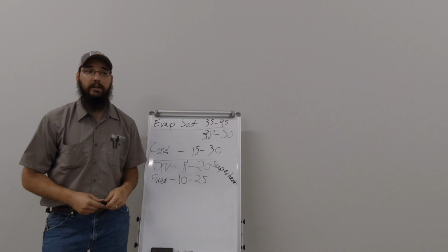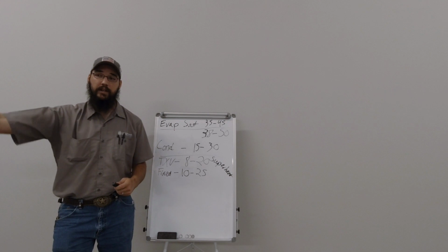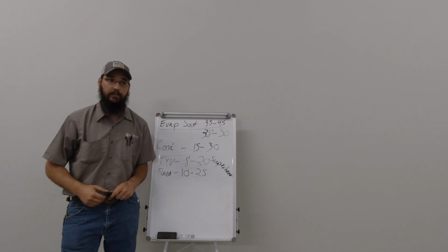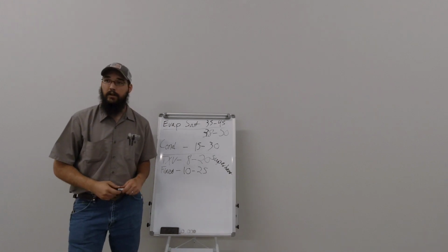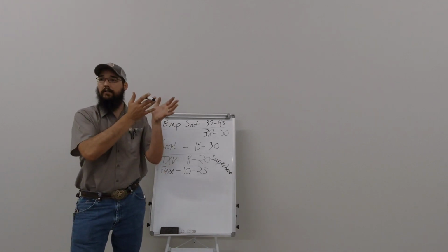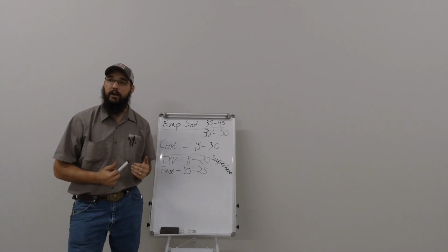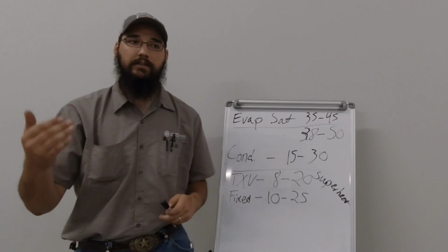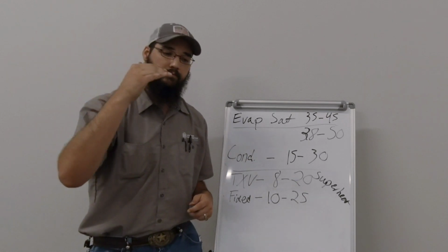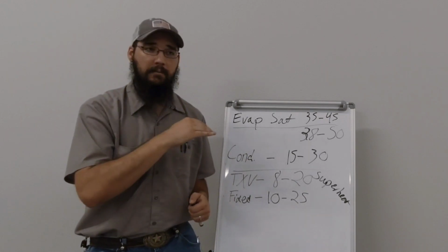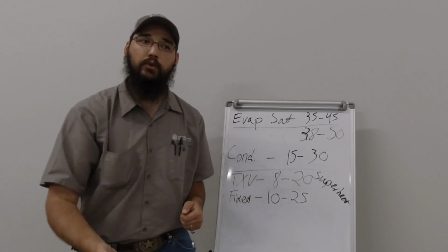The other way they can run is circuit 1, both compressors together without circuit 2. So next I'm going to stage off circuit 2 again, leave it off, and I'm going to bring compressor 2 on circuit 1 on. All right, so when I stage circuit 2 off, the pressures go back. When I bring compressor 2 on, I expect them to come back down in those same basic ranges. If at any point I see my saturation begin to drop too low, or my superheat is not maintaining a minimum of that 8 to 10 degrees, say I bring compressor 2 on